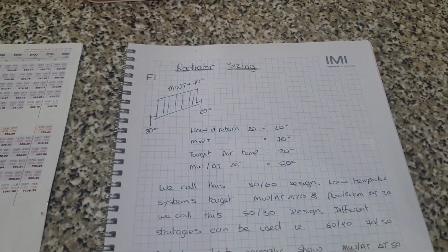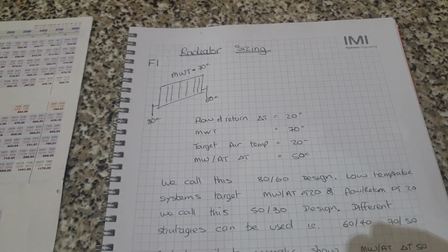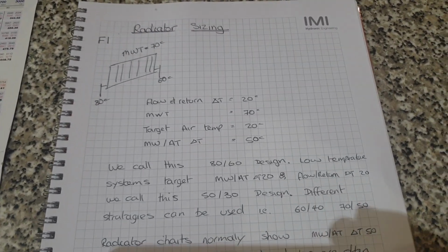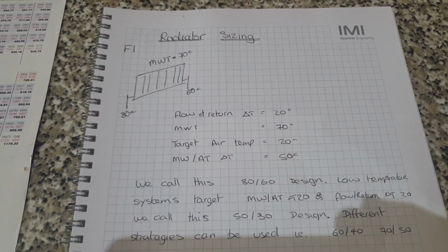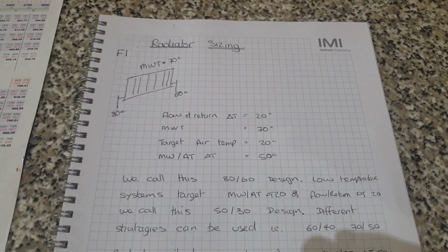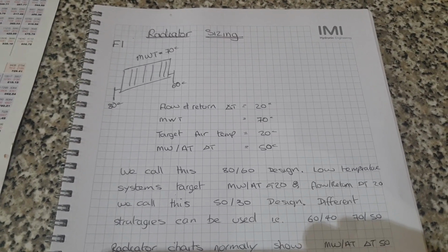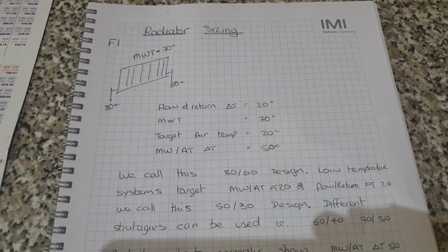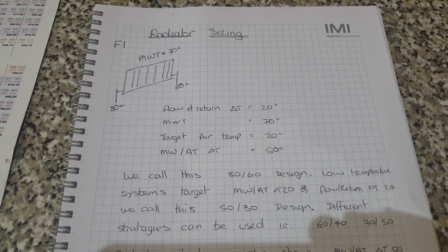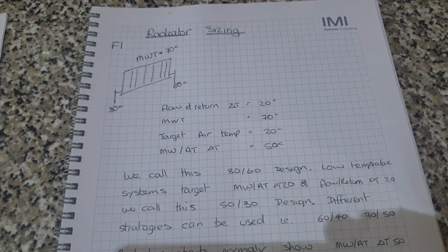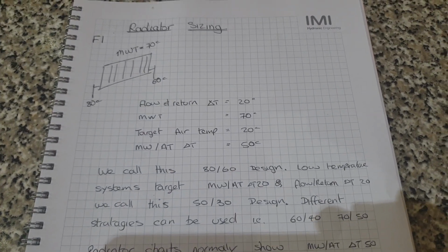Looking at radiator sizing, there are a series of factors, four factors: F1, F2, F3 and F4, and these give us values to adjust our calculated output of our radiator depending on the situation we're using. The most significant factor is our F1 factor, and the most interesting one, from my mind, after the F1 is the F2, and the F3 and F4 are quite boring. So I'm going to cover F1 and F2 in this, and I'll mention the 3 and 4 for you. If you want to know more about 3 and 4, have a look in your Domestic Heating Design Guide. Or if you request, I may do a video on it later, but it's really not that interesting.